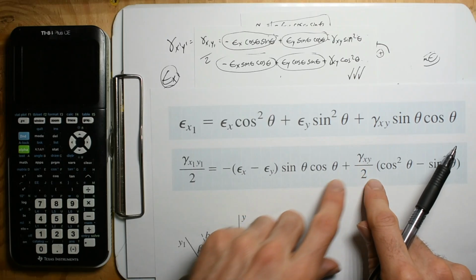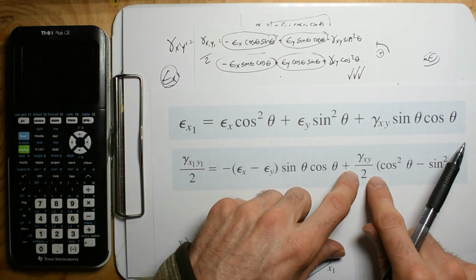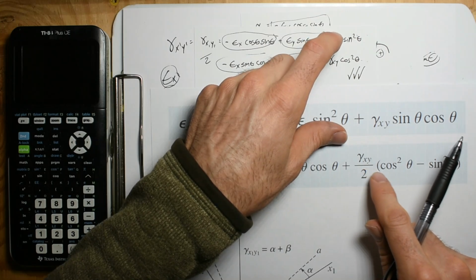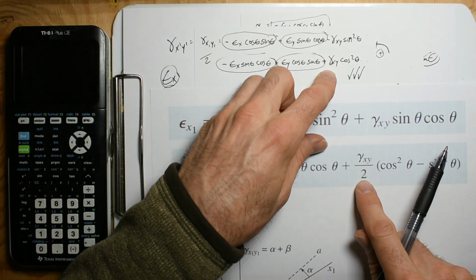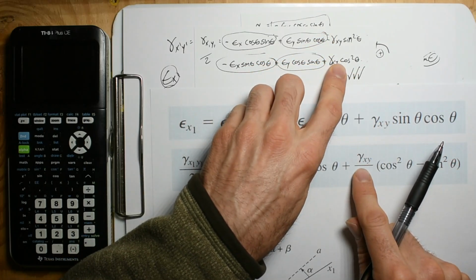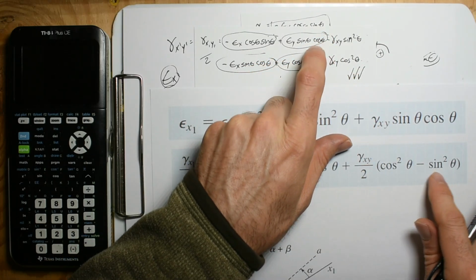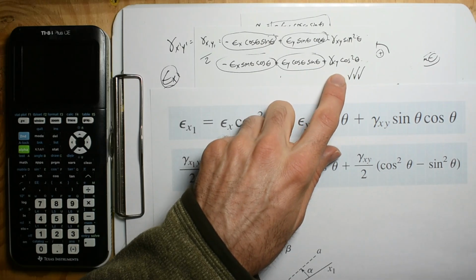But over here, when we take this as a function of just half of the shear, we're going to have these 2 terms, but then halved. What's common to both of them is the shear in the xy. We're going to have a negative sine squared theta and then a positive cosine squared theta.